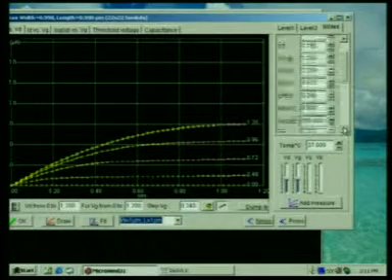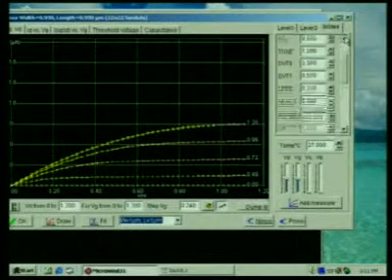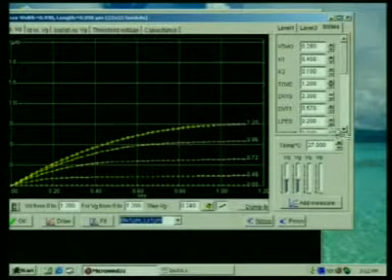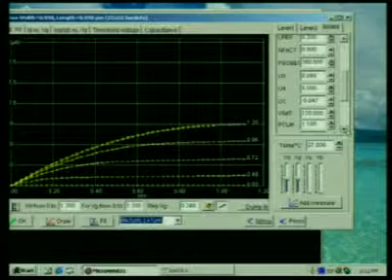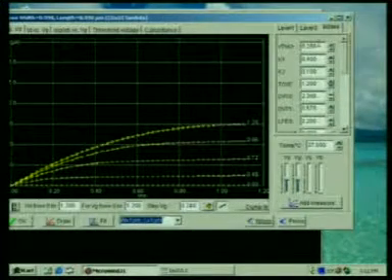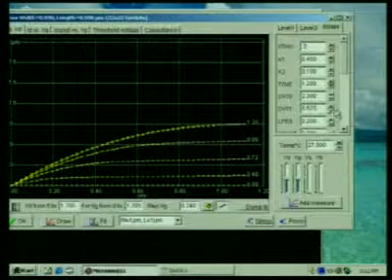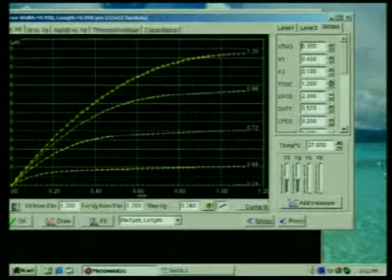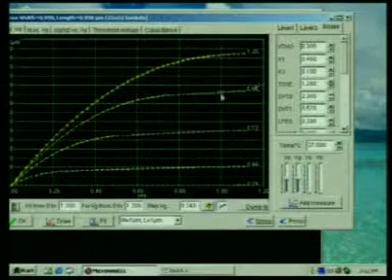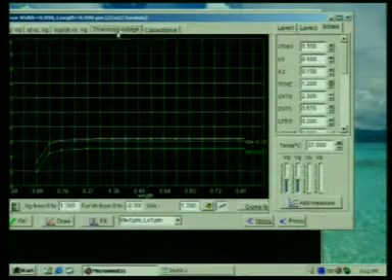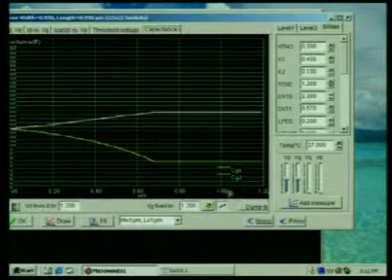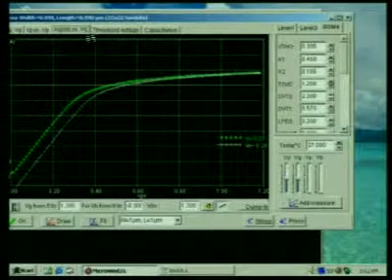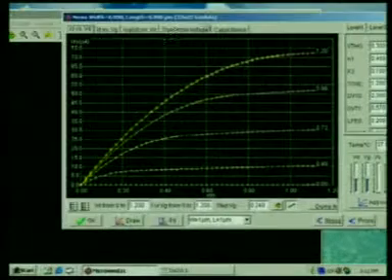These are the different parameters. You just edit them and you can check out the effect. See, this is the threshold VTHO, K1, K2, thickness of oxide, a lot of parameters. Suppose I edit this one to 0.3. See this, now it affects my characteristic curves. These are the various characteristic curves. You can check out the parasitic capacitance values, CGS, CGD relationship, threshold voltage, log ID versus VG, ID versus VG, and ID versus VD.